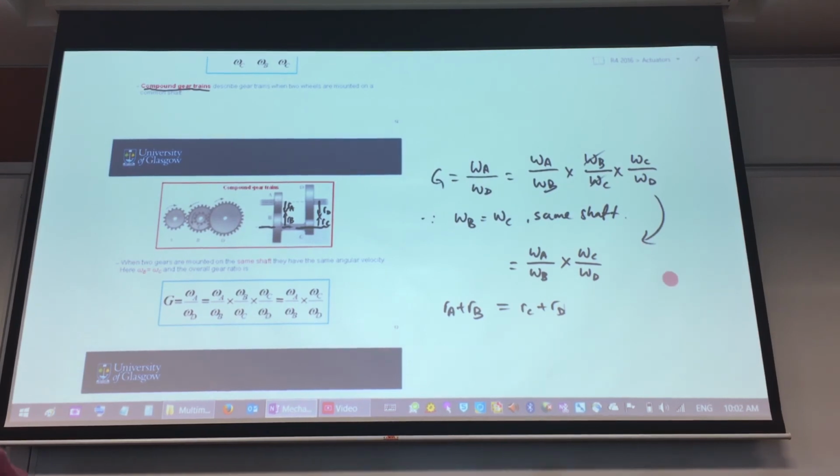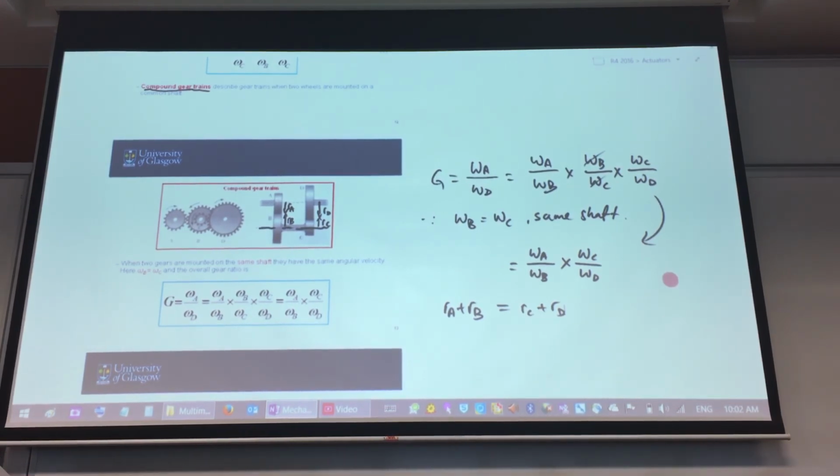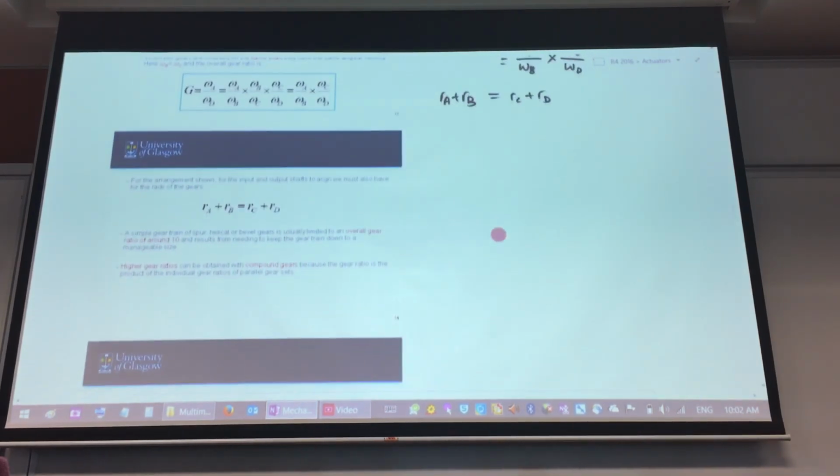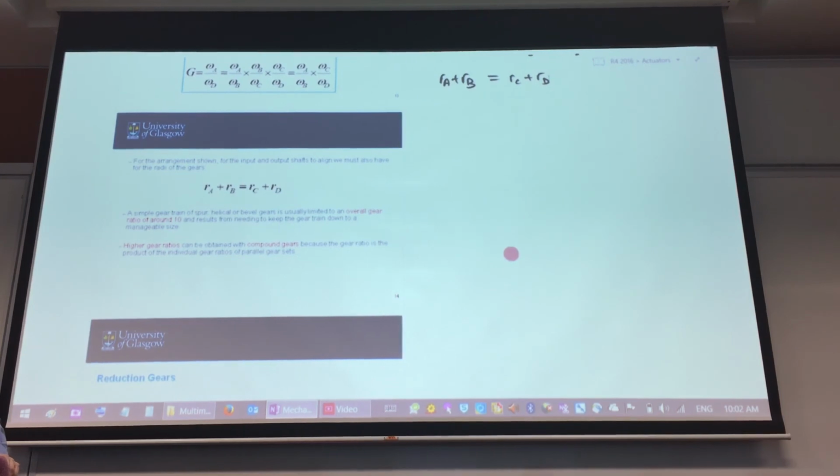But that's one problem. Compound gear, even though it has a very large gear ratio, being compound gear, has a lot of gears inside. A lot of gears inside means there's a chance of failure because there are a lot more contact points. The entire compound gearbox is also going to be a lot heavier. So these are some of the disadvantages that you can find for compound gear.